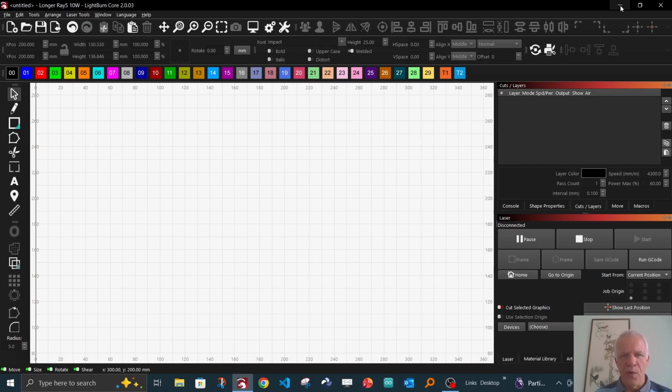So I'm going to show him, or you even, how you do it in LightBurn. And I've drawn a very, very complicated house, so please bear with me, but I promise you'll be able to follow along. So I'm going to open the DXF file. No, I'm not going to open it. You have to import it.